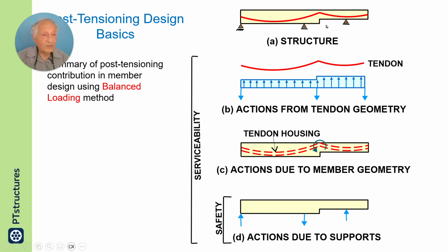Here at the top right, I have taken just a simple member supported on 3 points to be hyperstatic. If you take the strand tendon out, you will have the up and down forces. This is the simple load balancing. This is what was introduced in 1963, substituting the comprehensive method which was prevailing until then.